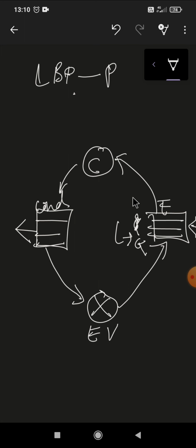Since the refrigerant is not hot enough to warm the target liquid, the compressor comes into the picture. The compressor raises the temperature and pressure of the refrigerant, because of the volume reduction, and forces the high temperature, high pressure gas to another heat exchanger called the condenser.